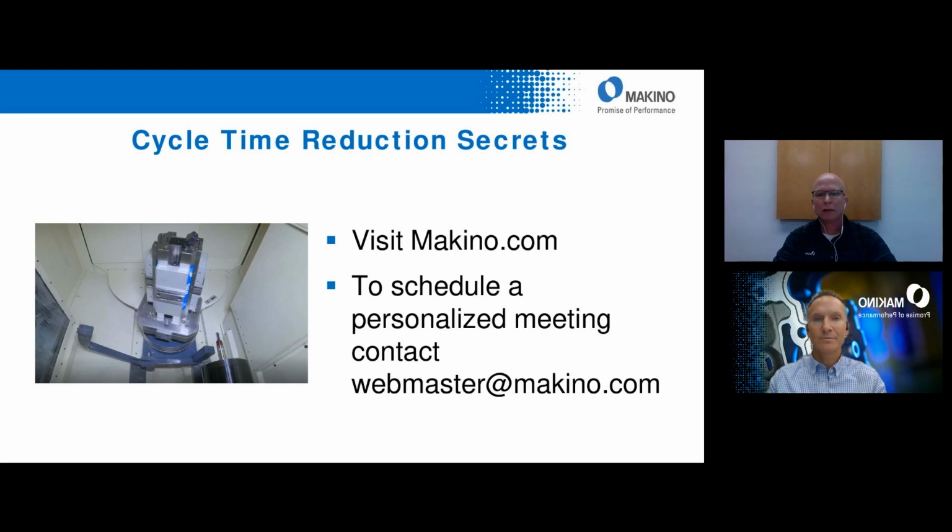That's a milliseconds timer, on all FANUC based controls. You reset that right before the motion you want to record. Then at the end of that motion or toolpath, you save that to a holding type variable. That's what I like to use, because that way I can go back and look at that variable and it doesn't get cleared out. So that's how you do it.